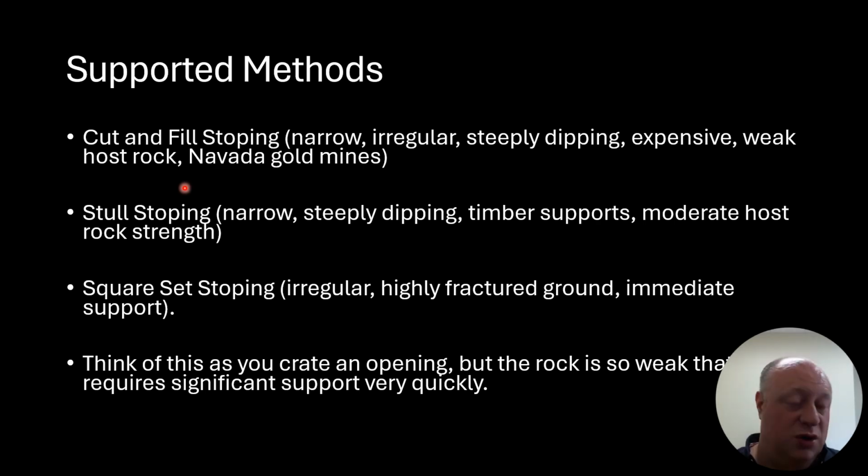So what you're doing is you take out a cut, you take out material, and then you backfill it with whatever. Sometimes you can use waste material. There's also paste you can backfill. There's like a slurry sand backfill. There's a number of options to use, but what it does is it supports the rock, right? The rock is not going to support itself. You've got to put something in there.